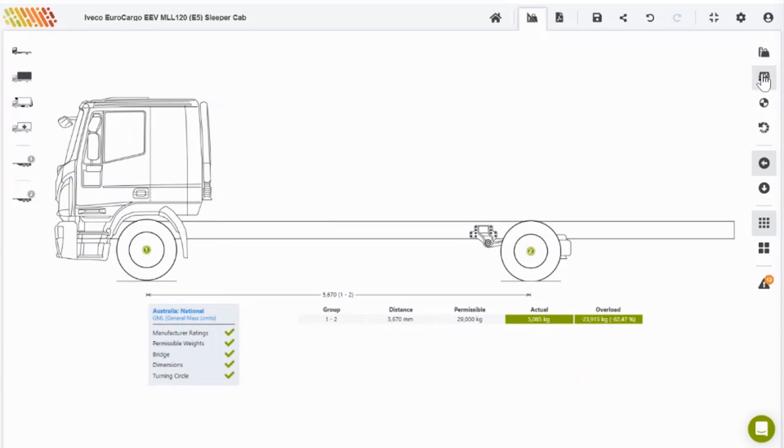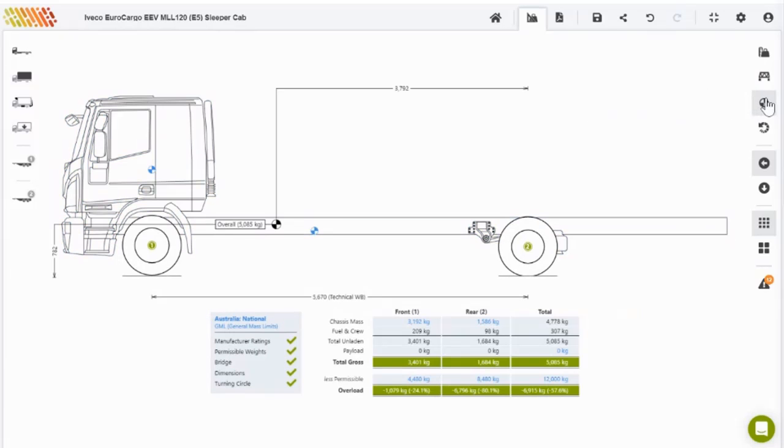It has a bridge formula for the markets that require that, and in some cases with different vehicles that will come in handy. Have a center of gravity as well, so depending if you've got multiple accessories or drivers or fuel tanks or pieces of equipment, then this will identify the center of gravity for those components. We'll also put those dimensions and points in the report that we'll see at the end. So for a particular customer, if it was after that, then we can provide that.